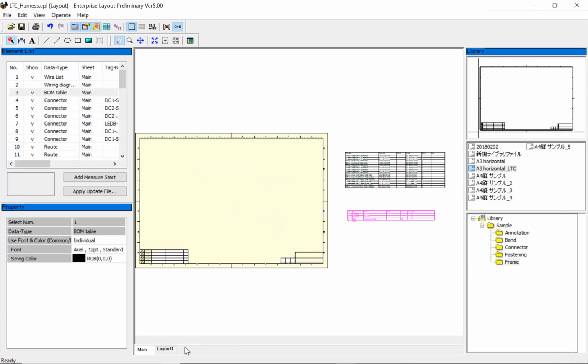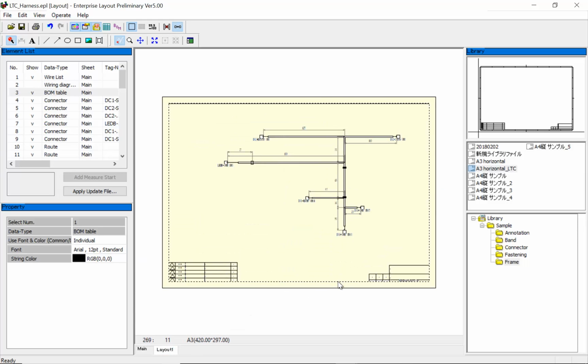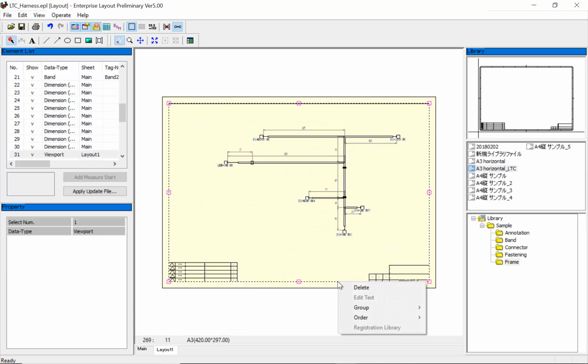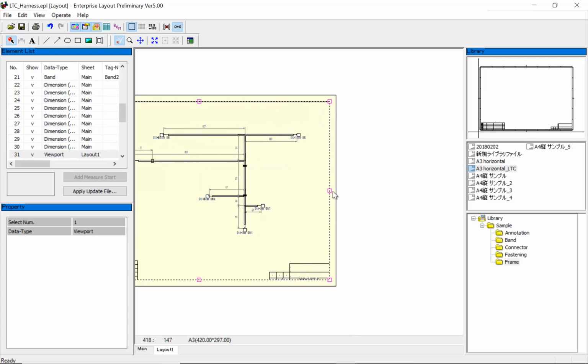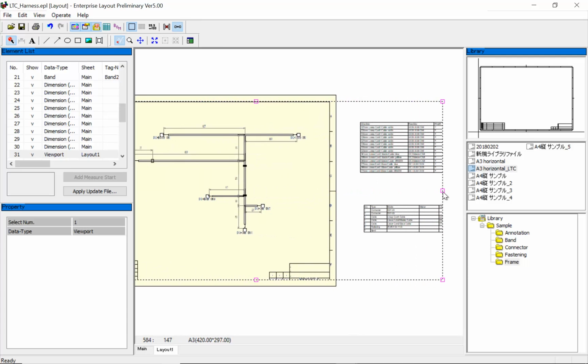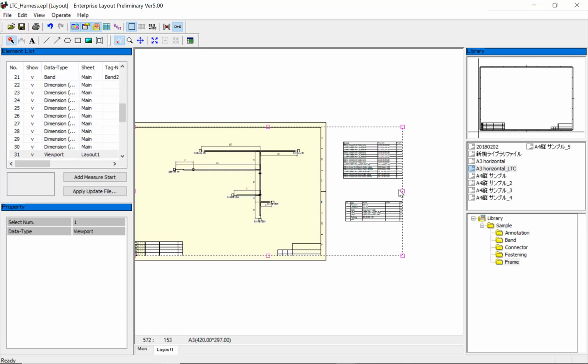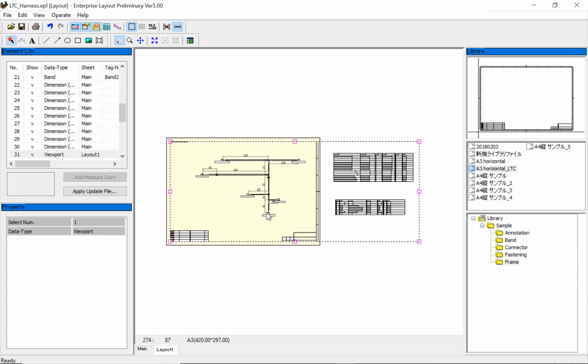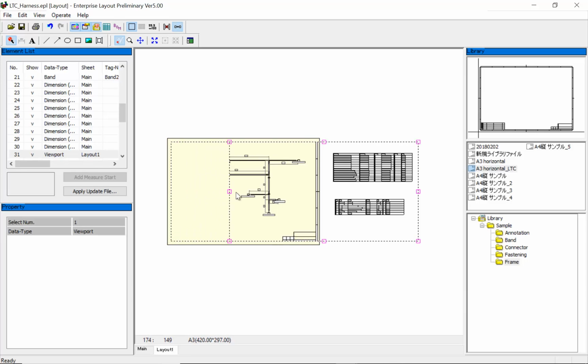On the second sheet, accessed from the tabs at the bottom of the drawing view, the viewport can be manipulated to focus on those tables so that they print clearly on a second page. This approach is similar to that used by AutoCAD and many other 2D CAD tools and provides detailed control to get the perfect printed output for the final design.